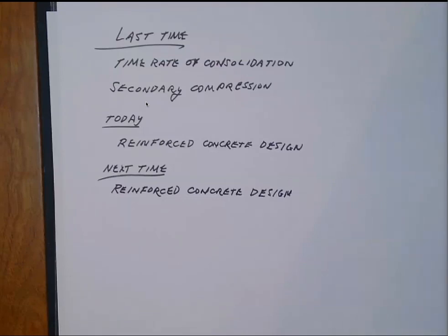The equation associated with that has a very similar format to that of magnitude of settlement, because it's a semi-log plot associated with void ratio on the y-axis. And it would just be time is what's going through the change. And the fraction that you have, log of a fraction, is still endpoint over starting point, except now we moved on to a time domain instead of a stress domain.